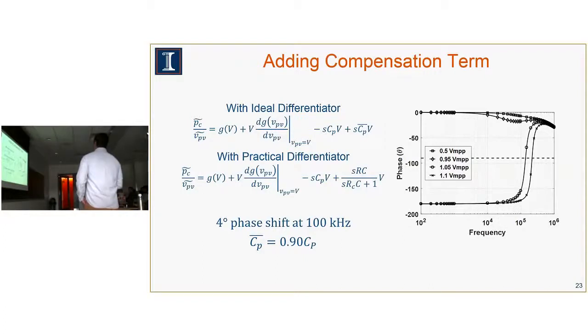It's tracking the phase difference between whatever the parasitic component is and our differentiator. If we can keep that at a relatively low value, then we can still push these transitions, which are undesirable because we're losing the phase we want, out past our switching frequency, and we can still increase the switching frequency of the converter.